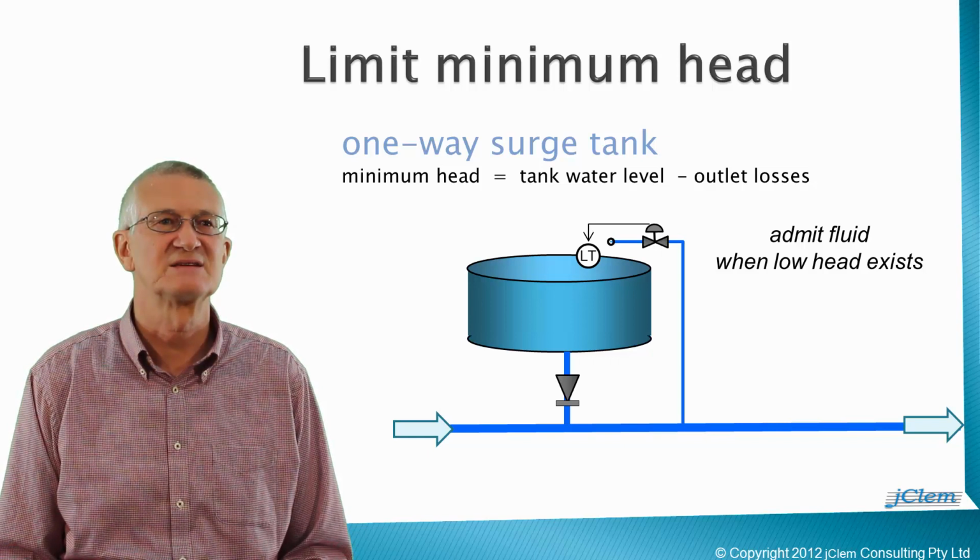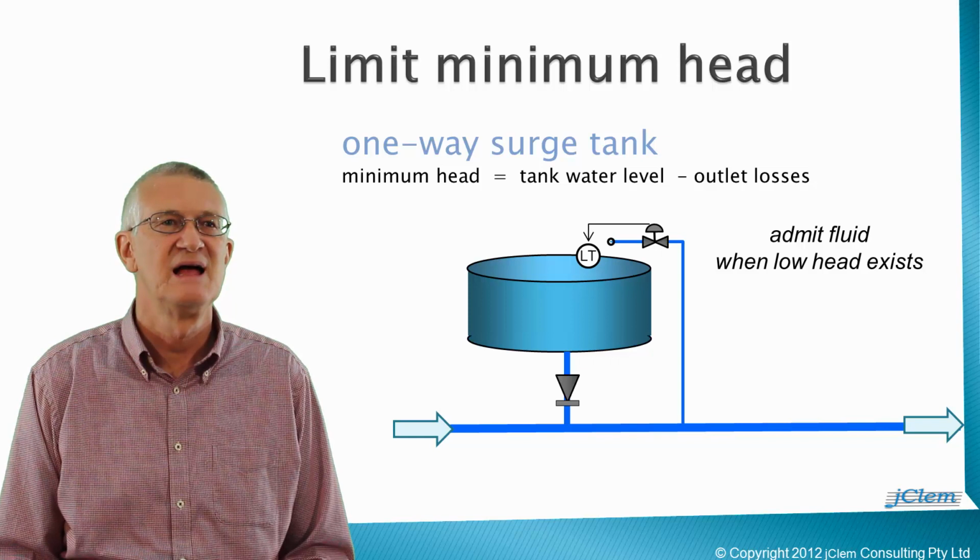One-way surge tanks may be a good solution on long effluent pipelines or raw processed water pipelines. They tend to be an undesirable solution on drinking water systems because water can stay dormant in the one-way surge tank for a very long time and can be a breeding ground for pathogenic microorganisms. Then a critical transient event occurs and the one-way surge tank inoculates the drinking water pipeline with these pathogens.